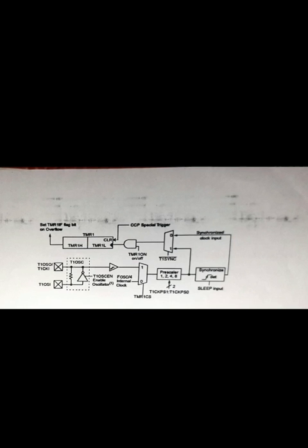The Timer 1 clock source bit is used to select the clock source. If the Timer 1 CS bit is 0, then the internal clock is given to the input of the timer peripheral. If you program it as 1, it will get the clock source from an external source. That external source can be the T1 clock input pin or